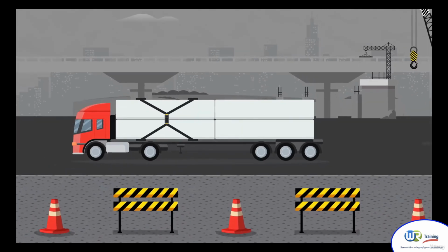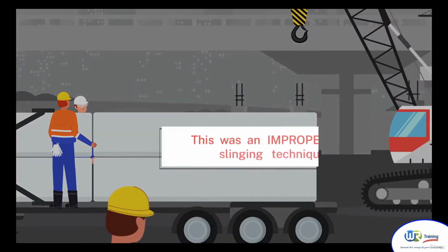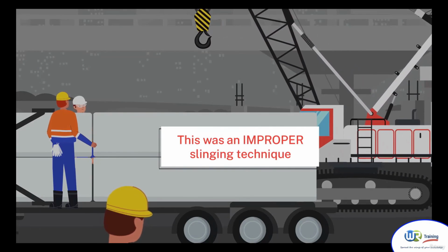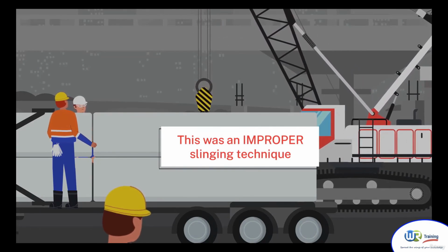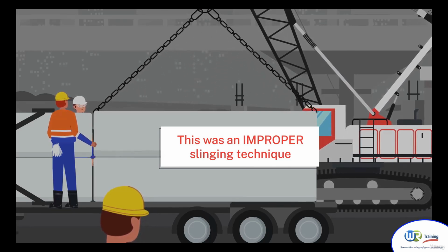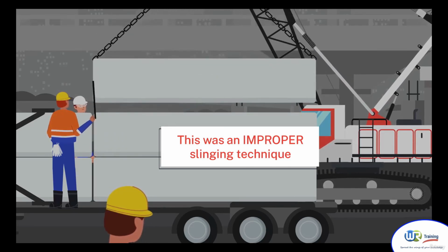The rigging method used to unload the casings was the handshake method. The handshake method requires the crane operator to place the crane's boom and hook over the center of the casing. The chain sling is then lowered to the casing, and one chain leg threaded through the casing's inner circumference, latching its hook to the hook of the second chain, like a handshake.